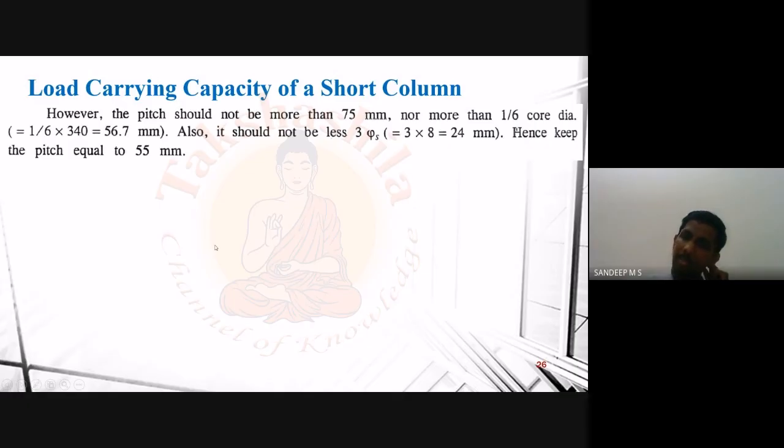Finally we have to show a detailing also. On top we will have the cross section. Then we will have 7 reinforcement bars, 5, 6, 7. Provide them uniformly distributed. Around this, we will have the spiral reinforcement, so you can just show a circle around this. Then you have to properly mark the diameter, the outer diameter. If you want, you can also show the cover. What is the cover provided? 40 millimeters.